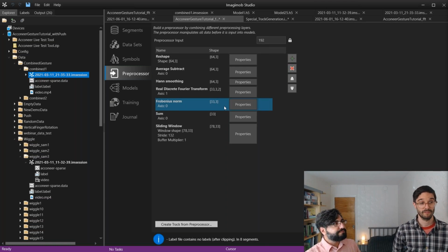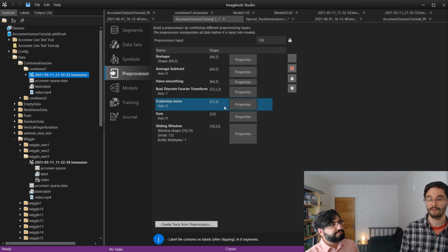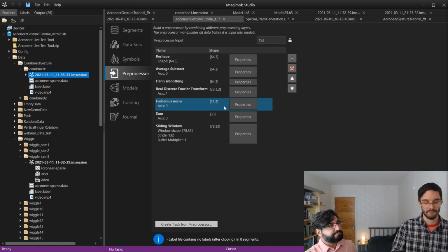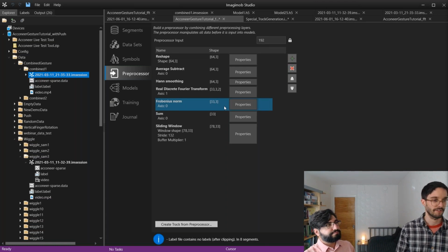But this is a configuration that you make in the radar sensor, right? Yeah. So you can set it up exactly like the question says here. You can configure the radar to collect data from a bunch of different distances and put the data into bins. So each reading we get from the sensor is actually a small amount of time captured from 3 different distances.